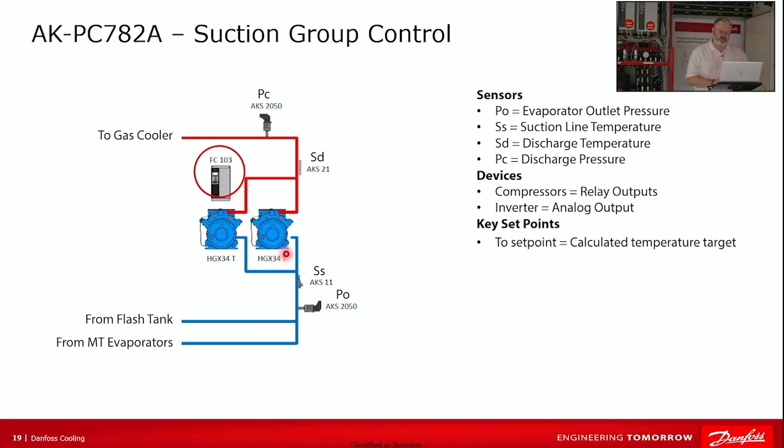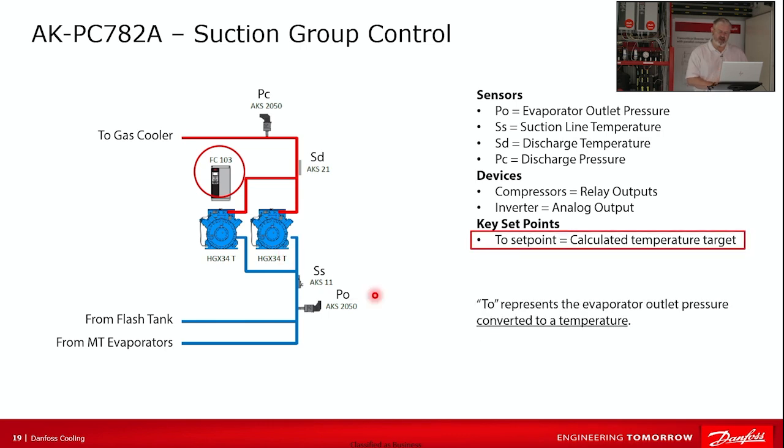The set points for the suction group are going to be the TO set point. That's our target temperature. It's something to note that this isn't the word "to," like going to the store. This is actually an acronym like we saw on the sensor abbreviations.